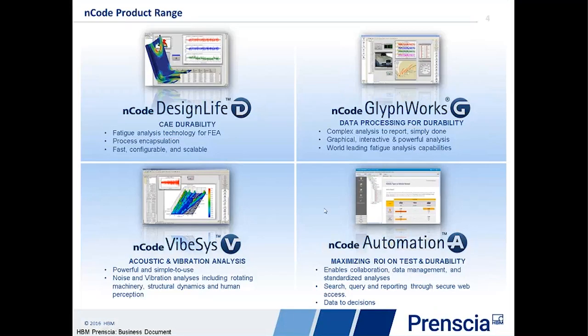First, allow me to show you just one slide about the product range we have in Prenscia, specifically the nCode product range. On the top left, we've got Design Life. Design Life enables you to do fatigue calculation from finite element result files. In finite element, you calculate stress typically, and in Design Life, you use those stress values to get contour plots of fatigue life, whether it's random, shaker tests, things like that. So we can simulate what's going on either on a shaker, a test rig, or in service.